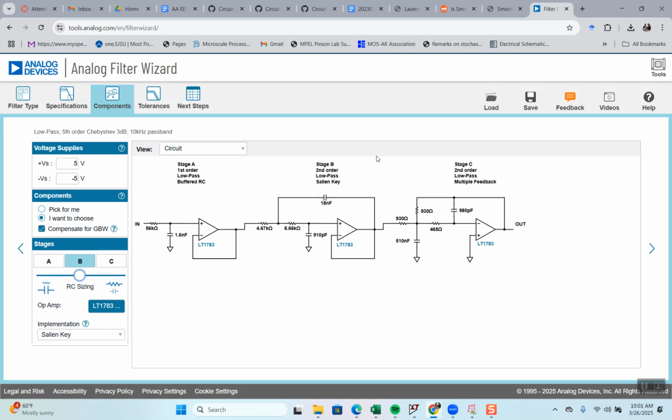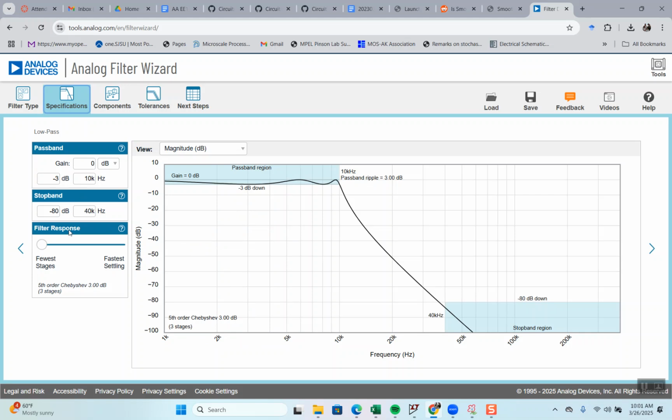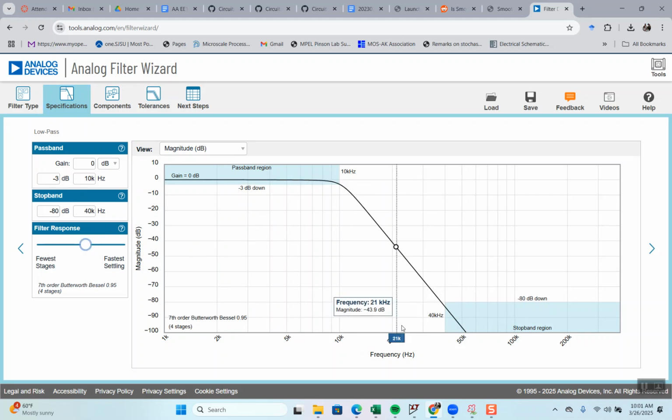Yeah. In the lab manual, though, I show you how to set the spec so that you'll get, I think, 4th order on purpose, or whatever order you want. I show you how to set the spec so it does what you want it to do rather than guessing. Because having an op amp just to have one pole is kind of a waste. You should get like 2 poles per op amp, I think. But maybe there's a reason for it. That's why they let you do it.